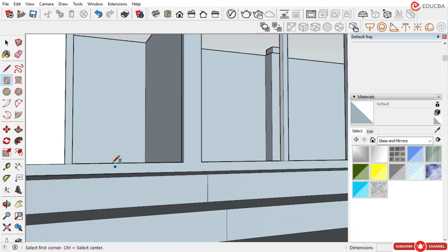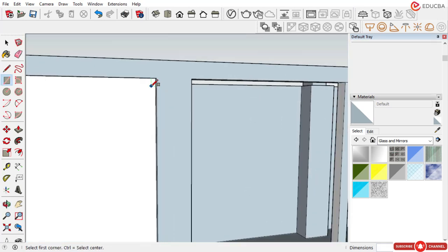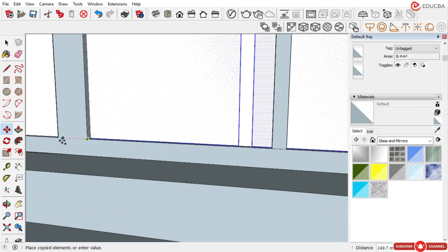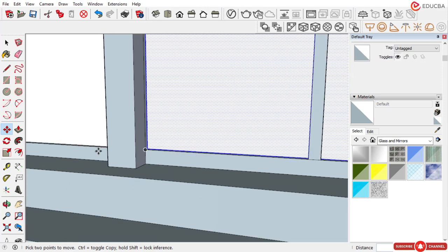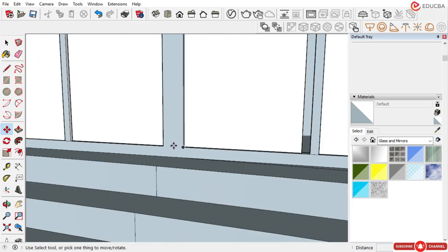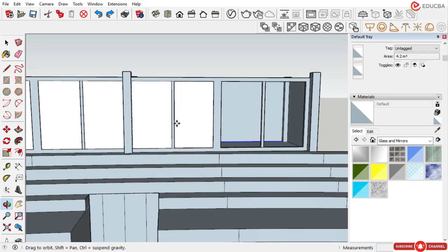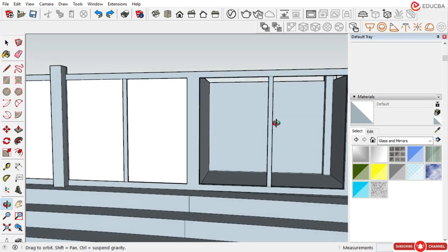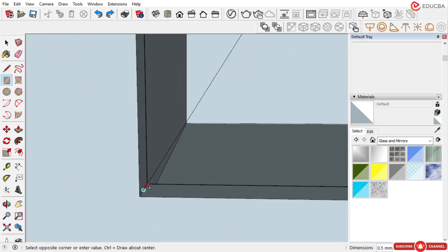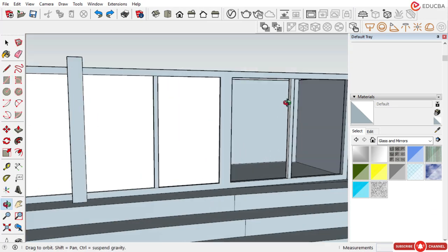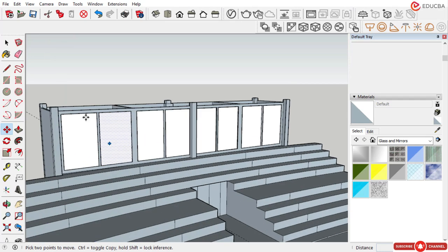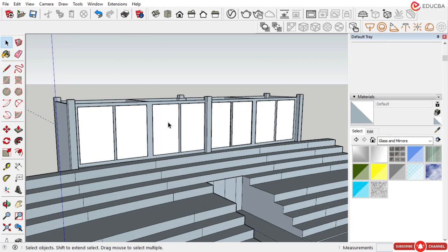Now design the rectangle for the mirror or the glass. So draw the glass to all the frame, here to here. What we can do, we can copy this glass, select, copy to here also, and copy to here also. But somehow the size is not matching this. Here we need to draw it separately, a different size of glass is here. So I have designed 4 numbers of glass, total 8 numbers of glass is there.